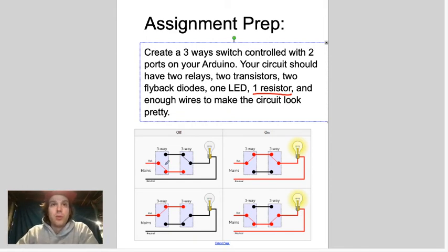Okay. Well, you have a switch. Basically, and there's many ways to wire a three-way switch. This is not the only configuration, because you can have the light bulb in between the switches, and it starts to get complicated. But it's all the same basic idea. It won't make much of a difference. Okay, so how it works is, as long as these 2 switches are connected to the same lead, the light bulb will be illuminated, right? So if you're in this configuration, you could turn either this switch up to here to make it connected and the light bulb turn on, or you could turn this switch down to here and it would connect and make the light bulb turn on.